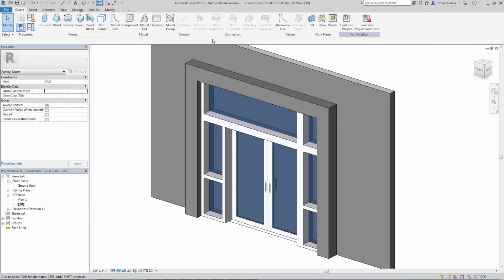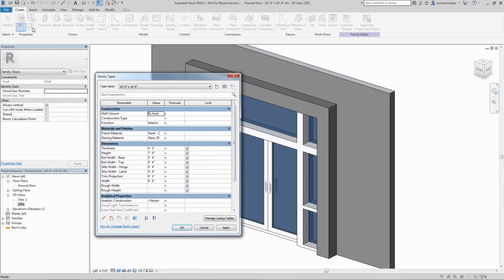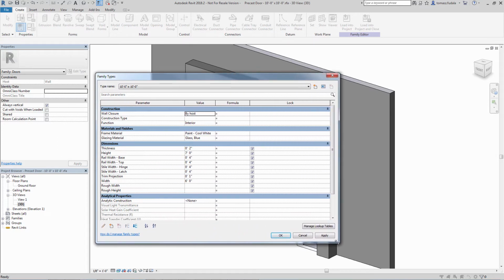When building Revit families, you may need to create complex formulas to write family parameters and types. Formulas can get lengthy in the Type Properties dialog, and it is useful to adjust the size of the dialog's column width so that the entire formulaic value can be seen.